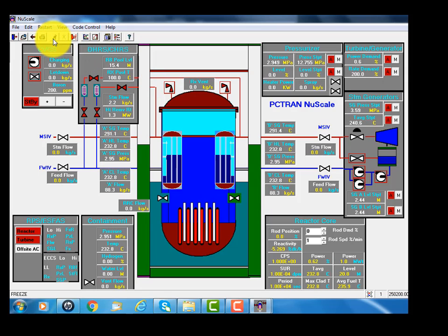And we can accelerate the cooldown by opening the reactor vent valves. All right, so the steam will fill up the containment. Remember, containment was originally vacuum, and now it's filled by reactor coolant. And the hot water in the containment transmits by conduction to heat the pool water. At the same time, steam is cooled by natural circulation through the heat removal system.